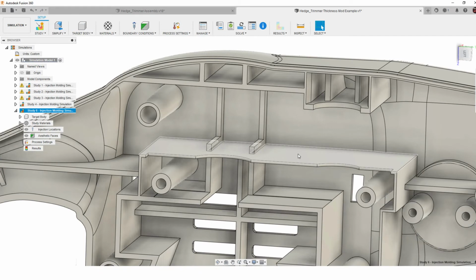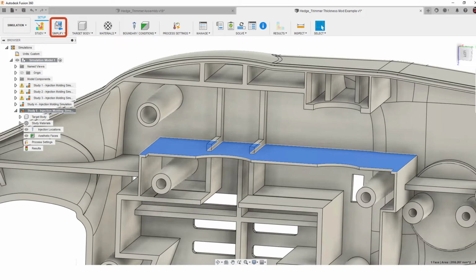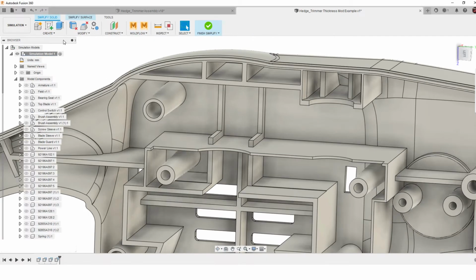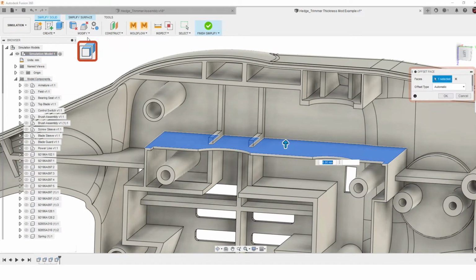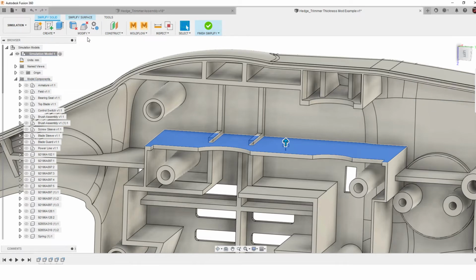Similarly, and in reverse, you will have warpage concerns where there are areas of the part that have thinner wall sections because they shrink less than the thicker sections. If there are more thicker walls in the vicinity than thin walls, it may make more sense to increase the wall thickness in these local areas to help reduce the warpage.